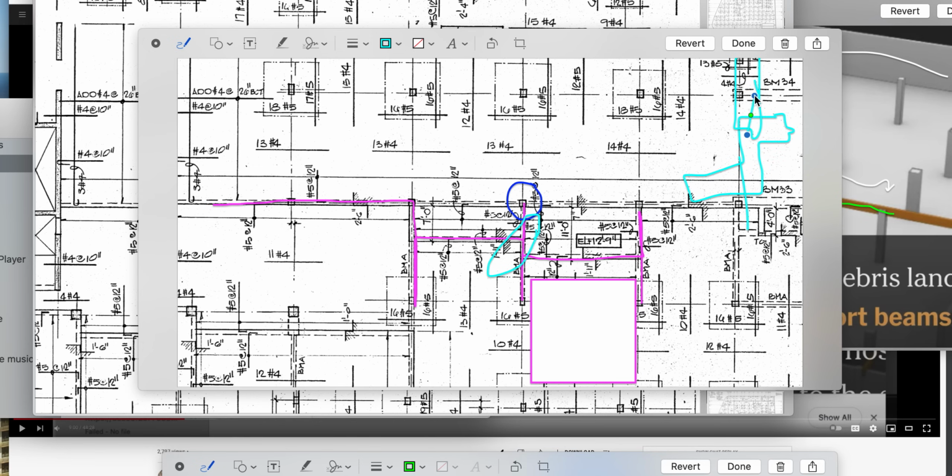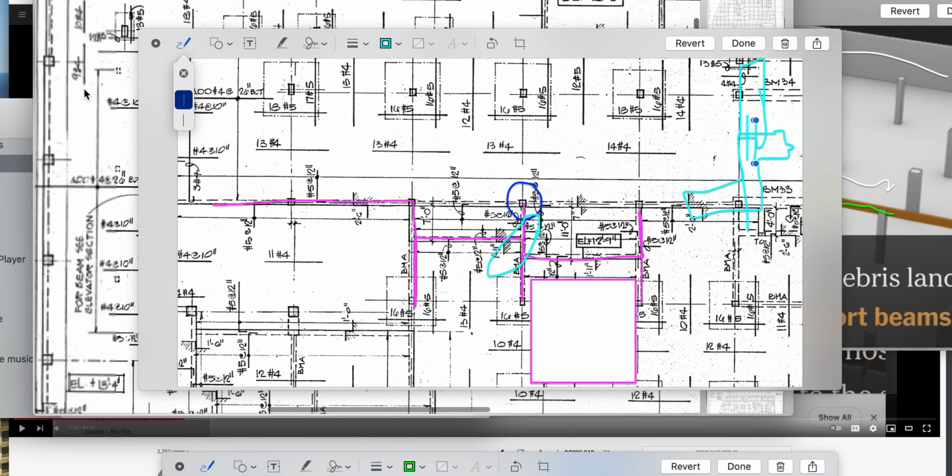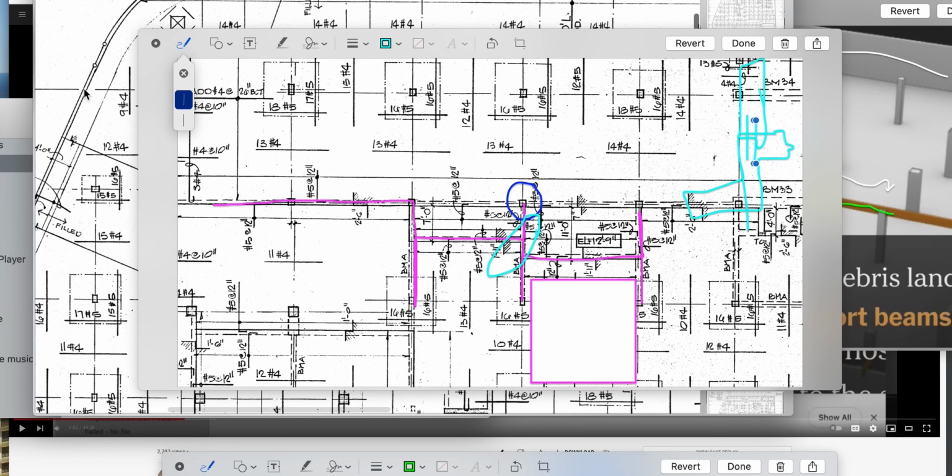Was the column down here, and then it picked into the side of the column, or was the column on top, or was the column right there and then the slab transferred through it? The drop detail shows like this, though, but it doesn't show how the column is anchoring. So these would have been heads sticking up, rebar sticking up from here. It doesn't quite show in the details of the drop slab details of this system.